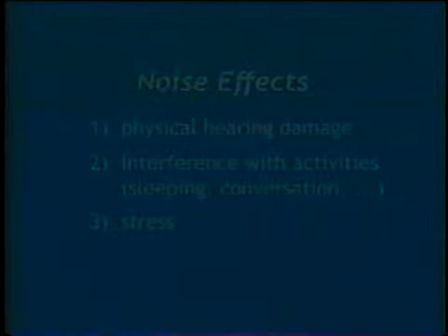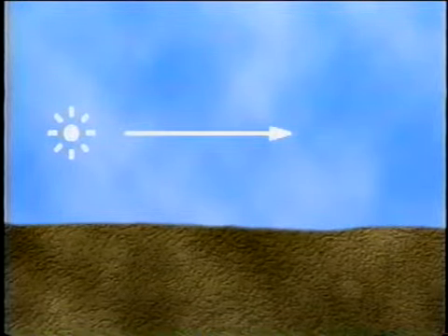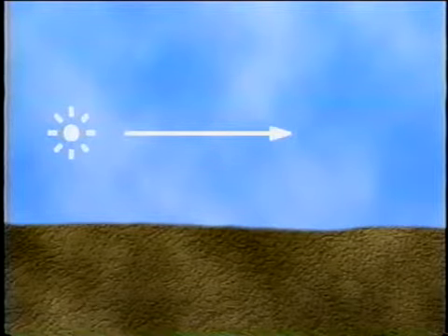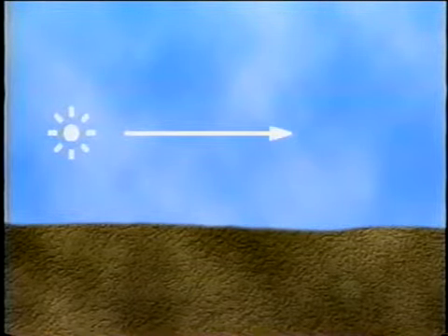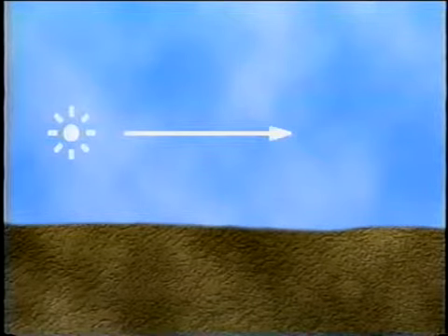The path the sound takes when traveling from the source to a receiver can be quite complicated when taking into account ground reflections, obstructions, and meteorological effects. The received sound level depends heavily on these parameters. We can start by talking about a simple propagation path, the path going directly from the source to a receiver. Besides geometrical spreading, which causes the sound level to decrease as it propagates toward the receiver, the propagation medium itself can possess inherent losses.